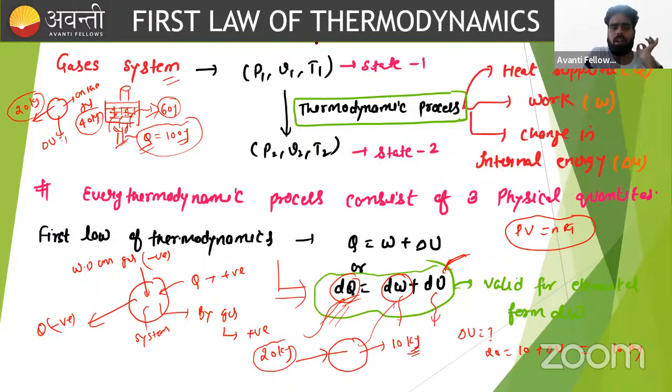Find the change in internal energy. Come on, what is the change in internal energy? Again we apply this formula, and we have to consider the signs. Very good. This is rejected, so we can say minus 20 equals delta U, plus delta W, work done on, so minus 40. So again that is the correct answer. I hope this makes it understandable to you.